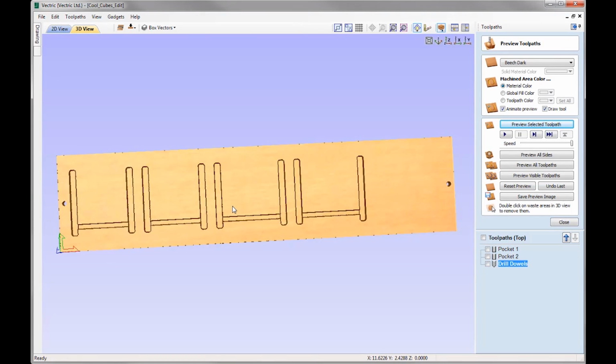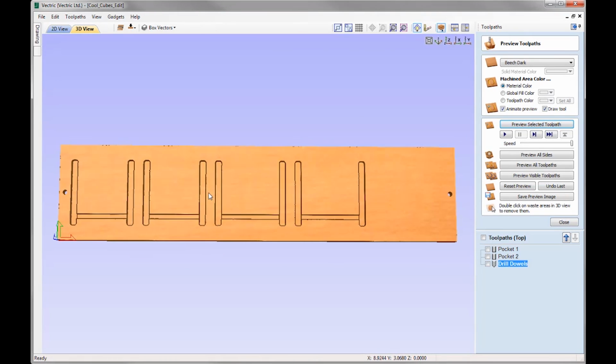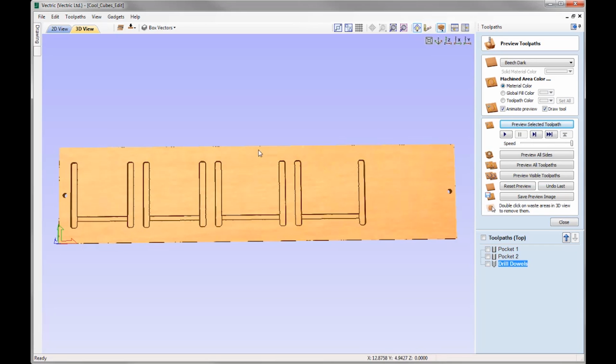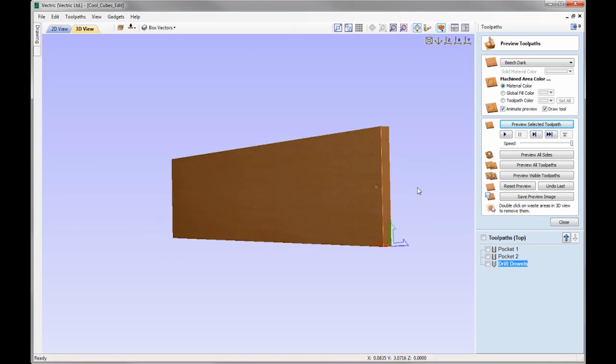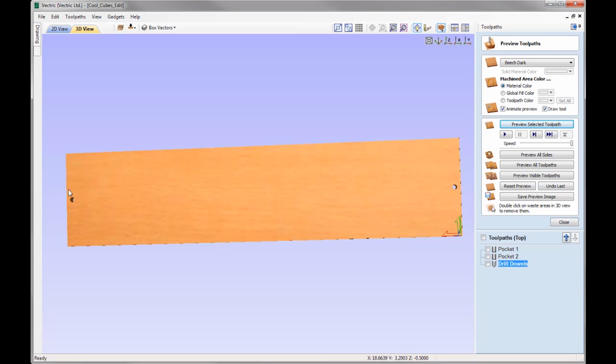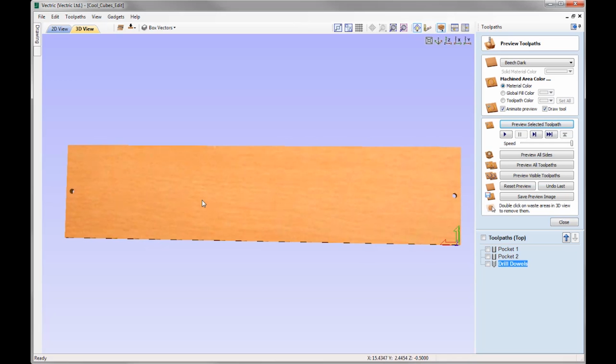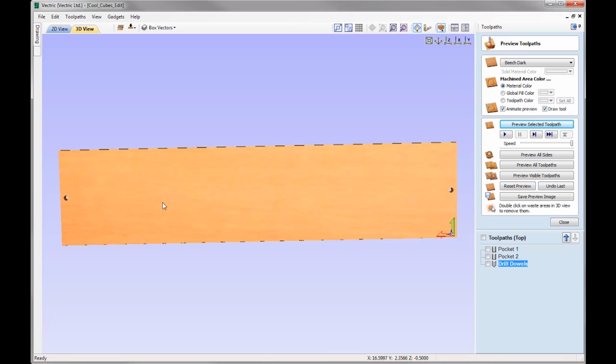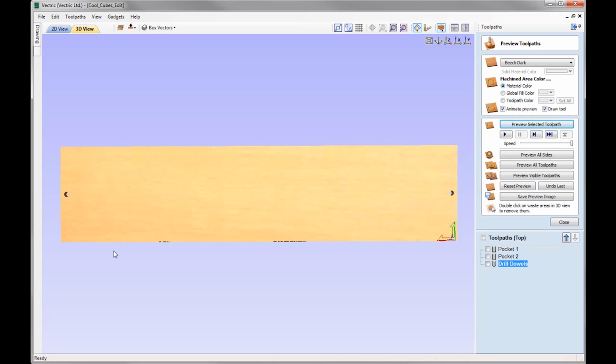So at this point, what we'd do in terms of the physical setup is we'd take this material block off of our machine bed and we'd insert the dowels into the holes that have been drilled into the spoil board. And then we'd take our material and we'd flip that over, and then we'd position that and align it to the dowel holes where we'd secure that in place. And because we've aligned it to the dowel holes, we know that our XY coordinates are going to be aligned with each other. And then we'd look at running the toolpaths for the bottom side.